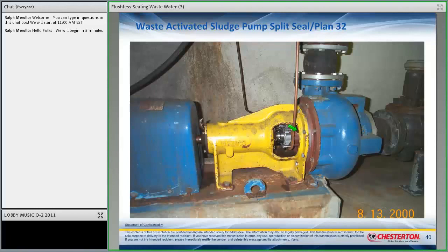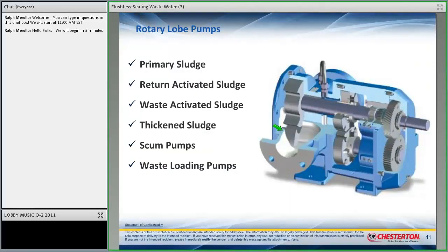So what's interesting about that one is they also have another line here going into the seal. So they're cleaning the area in front of the bushing, and they're putting fluid around the seal in the back of the bushing. So it's kind of an interesting way to do it. Thought that was different. I figured I wanted to share with folks. Absolutely. But again, they're flushing too, right? So we're trying to minimize that.